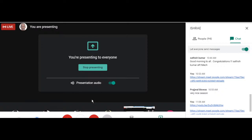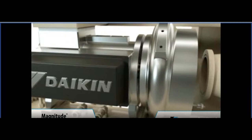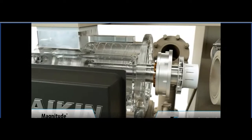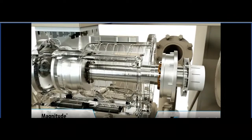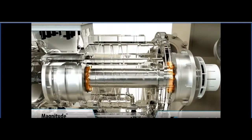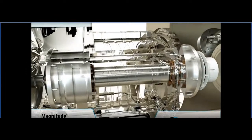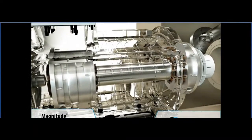The Magnitude chiller's exceptional efficiency is a result of the direct drive magnetic bearing compressor technology that eliminates the friction inherent in traditional centrifugal compressors that reduces efficiency. A digitally controlled magnetic bearing system replaces conventional lubricated bearings.